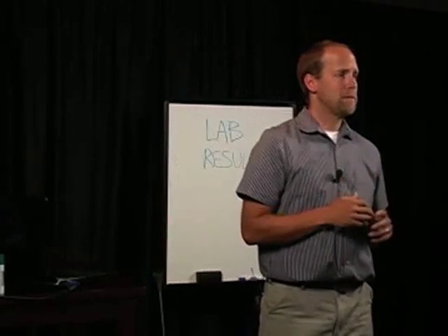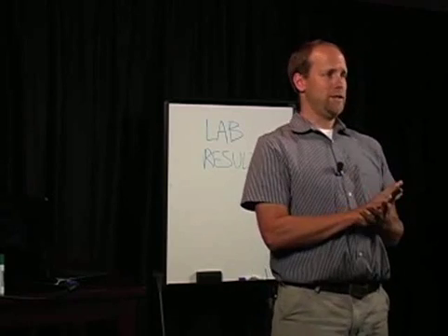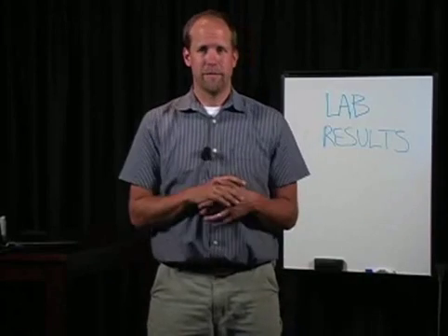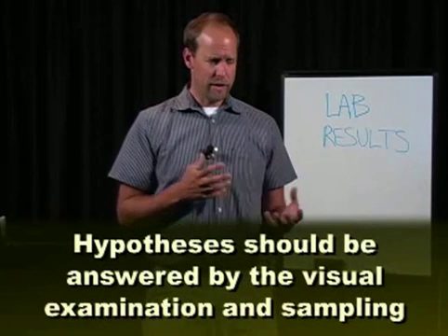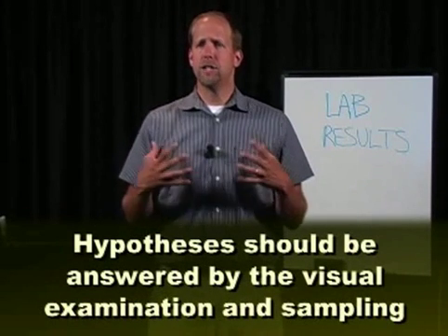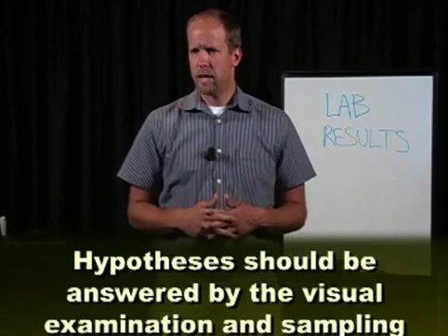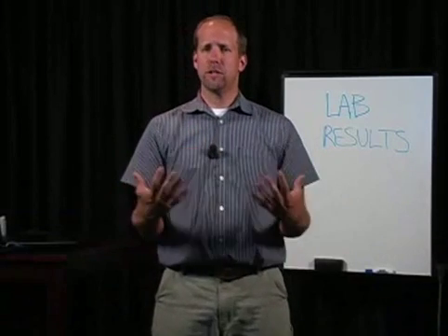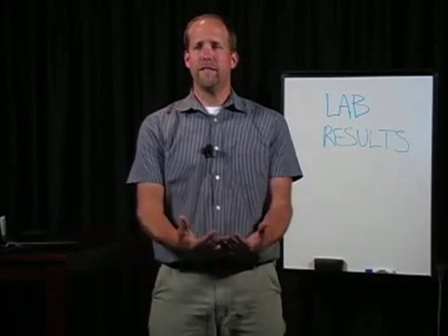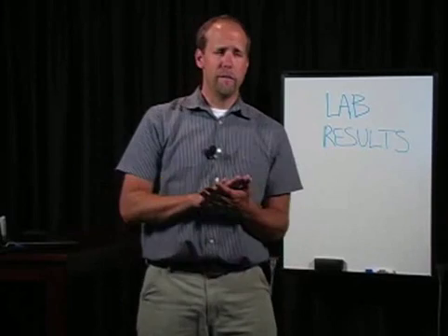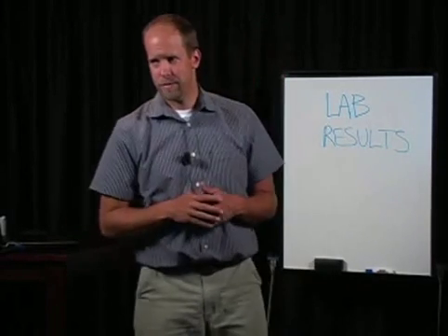Sampling results. Hypotheses should be answered. Mold inspectors should consider the results of the sampling, surface and air samples, in conjunction with the building's condition to decide if the information supports the hypotheses that have been developed and if the information warrants a recommendation for mold remediation.